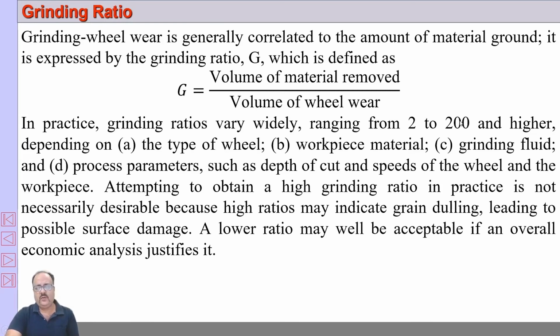However, it is normally around 95 to around 150. It varies within that particular region, and there are various factors on which this depends: the type of wheel and the workpiece material, the grinding fluid used or not, the process parameters like depth of cut, speed, etc.